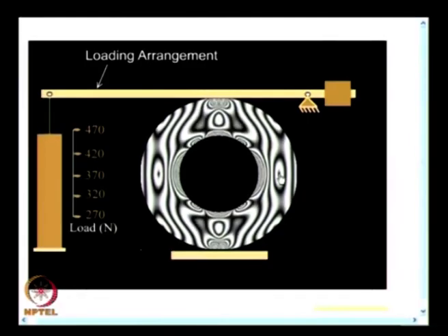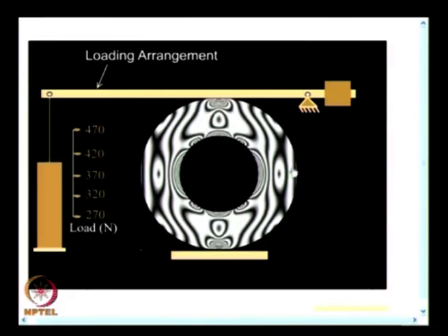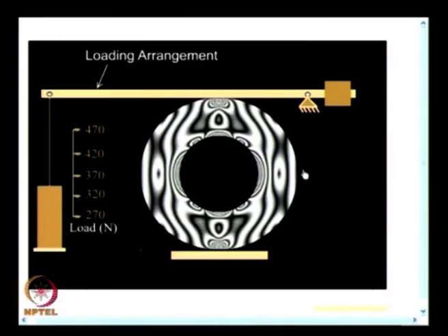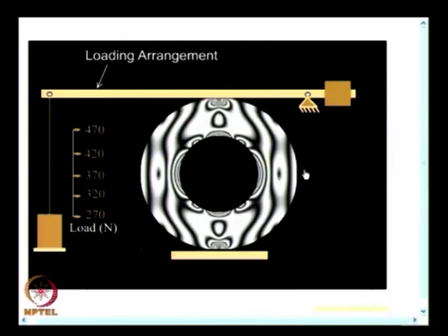If I take a color image of the fringe pattern using white light as a source, then a black spot in a circular polariscope will definitely say it is the zeroth fringe order. If you have a white light source, it is well and good. But if you do not have one, you should also have methodologies to identify the zeroth fringe order. But in this case, even if I know the zeroth fringe order, if I do not know how the gradient is along this direction, there is no way I can label the fringes.